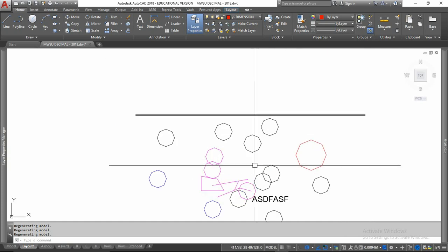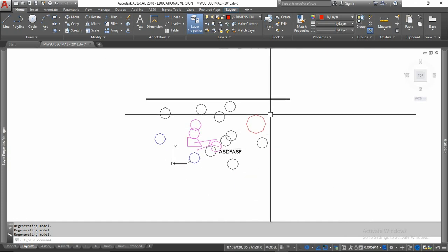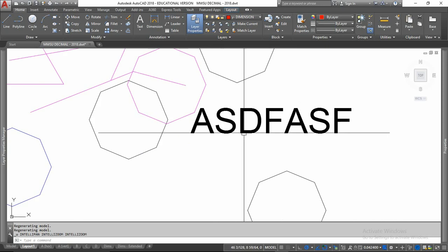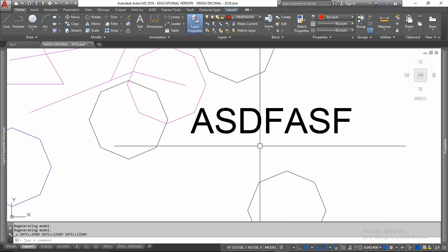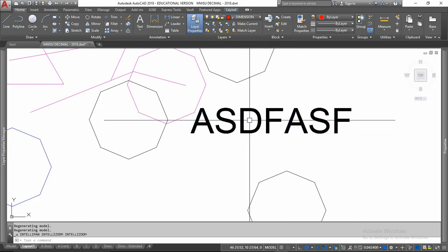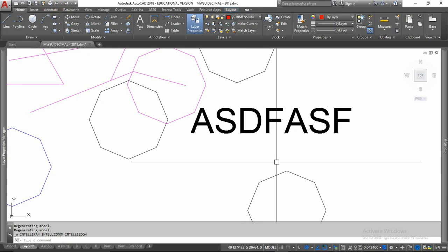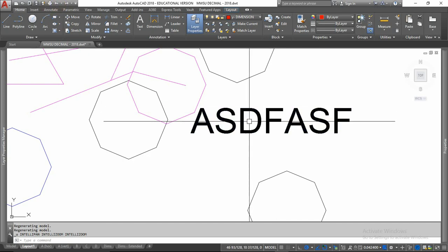And so zooming in and out, like you've seen, I'm still in my viewport. I'm just now zooming in and out what would be considered the model space. A couple things to fix this. One, if you do accidentally do it, undo, do a Control Z for undo, and or come up here on your quick access toolbar to get back where you were. Now, a couple ways.